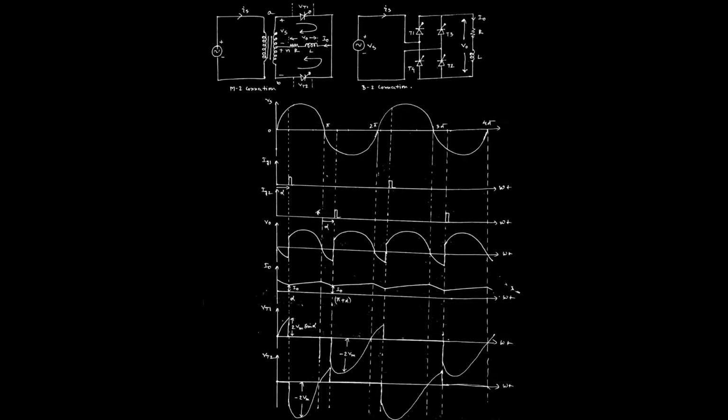Let me discuss the whole thing by using KVL. If we apply KVL across this whole loop, starting from the voltage for the forward biasing condition, that means Vs should be equal to the voltage across this switch, VT1, minus V2, minus VT2. Why have we taken the minus term? Because the position of this thyristor is opposite.